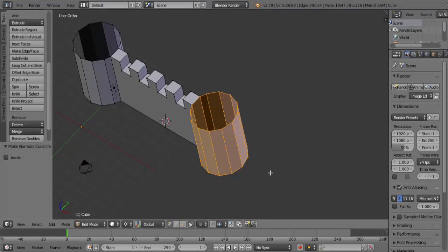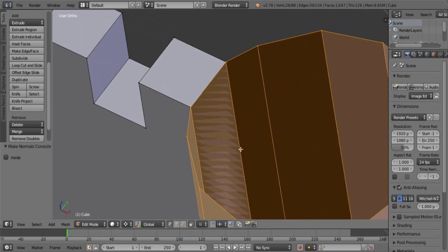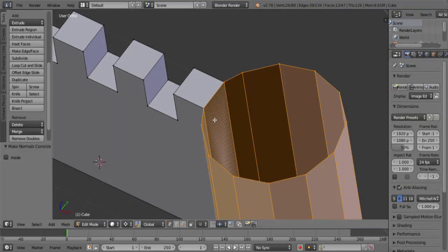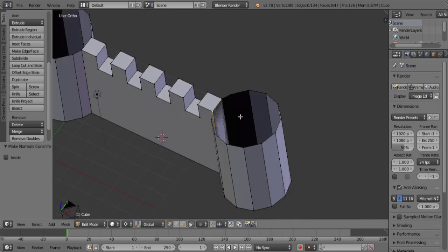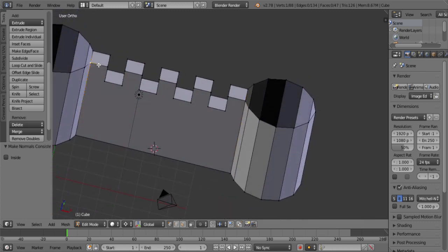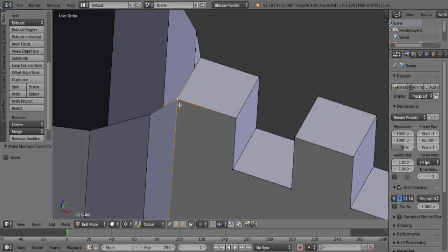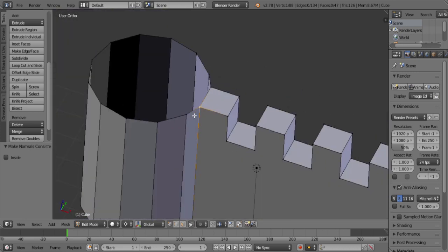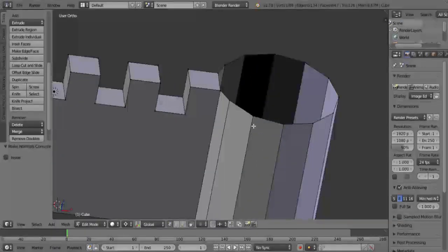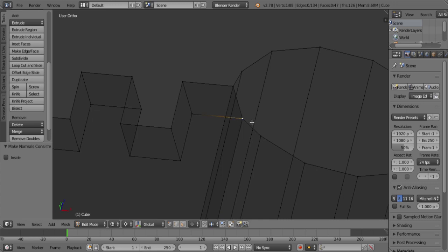And there's another problem. There's something wrong here. Let's take a closer look. I'm pressing Z. This tower is not part of the wall. It's not attached, unlike this one. Here you can see that all the lines are connected with this single vertex due to its orange shading here. If I move over to the other tower here, I press Z and right click one of these vertices and click again. As you can see, the tower is not connected.